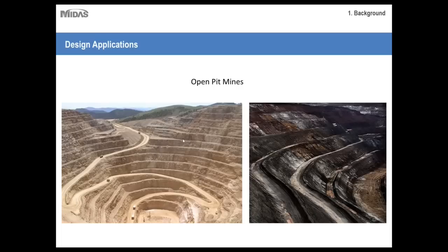Okay, then open pit mines. Open pit mines, or open cast mining, is a surface mining technique of extracting rock or minerals from the earth by removal from an open pit or borrow. As you can see, open pit mines are dug on benches, which describe the vertical levels of the hole. These benches are usually at 4 to 60 meter intervals, and the size of the machinery being used will determine the width of these intervals.